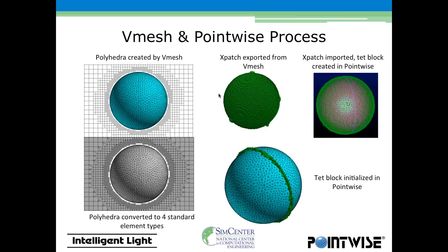On the left side, on the upper left, you see the voxel mesh that is created. It's a polyhedral mesh. In other words, it's hexahedral shaped elements, but they're not always just 6 faces. Sometimes there are subfaces and so on. So I store it as a polyhedral mesh. And you'll notice that it quits just before the surface mesh. So the volume mesh is created everywhere, including inside the body, and then it will go back and detect which elements are intersected by the geometry or outside the computational domain and remove them.